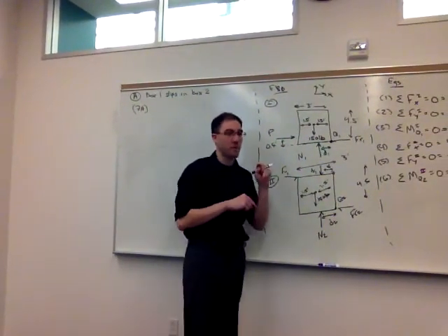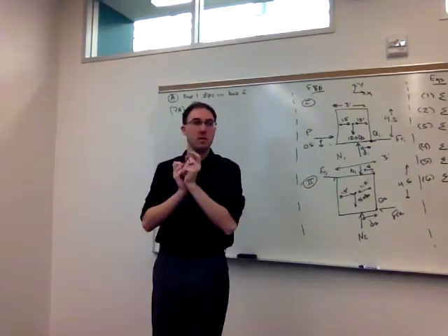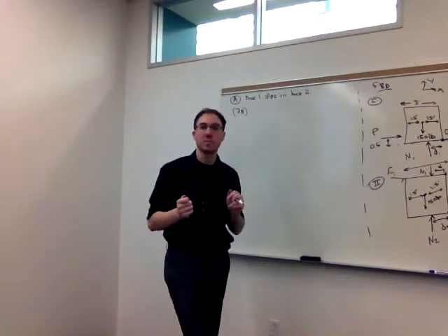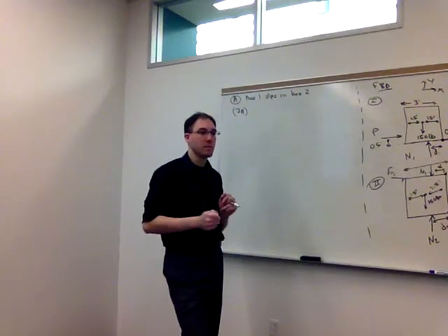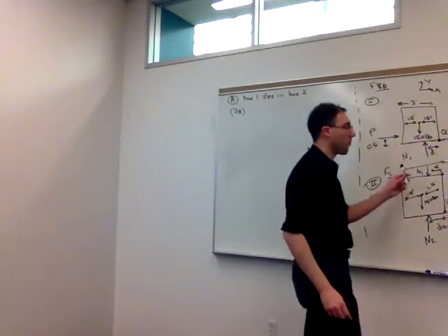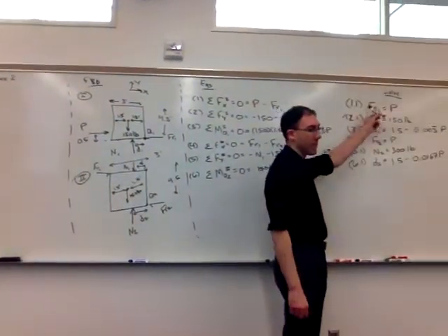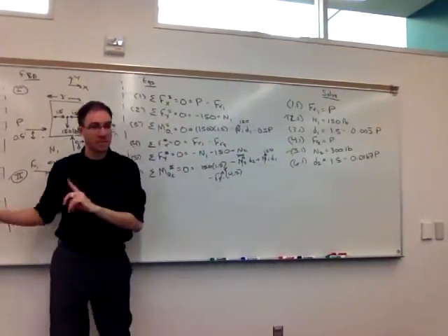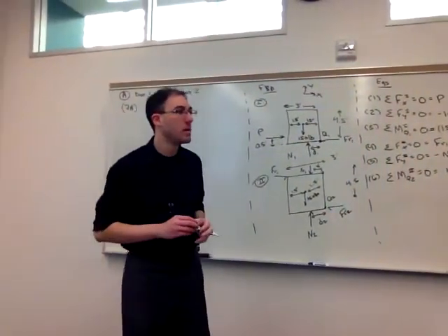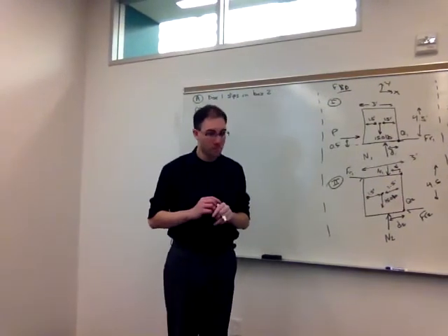There are 2 frictional forces, so more specifically, FR1 must be, well, it's always equal. If we're in equilibrium, we already know it's equal to P. So that's true no matter what scenario is taking place. Yeah, mu s times N1.